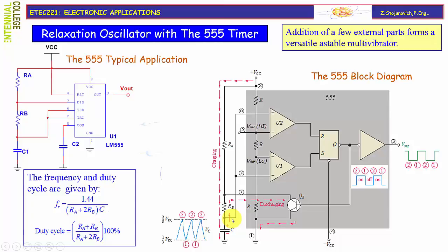The more sophisticated and more versatile type of RC relaxation oscillators come in the form of the integrated circuit 555 timer. This timer has several modes of operation, but we will focus on the astable multivibrator option. For this option, there are only a few external components required to provide a reliable and stable oscillation. However, the output will always be only a square waveform.